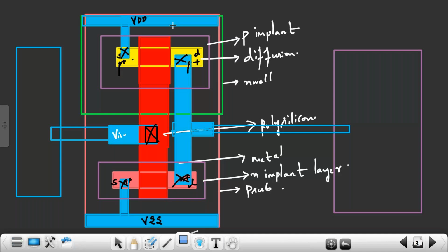So first 15 days they will only fabricate base layers. Even in those 15 days we have time to do changes in the metal layers. Still we can do changes. Later we'll send metal layers to the foundries. So we'll send GDS file in two steps. One is base layers. Next is what? Metal layers.